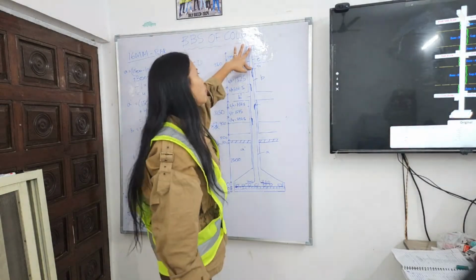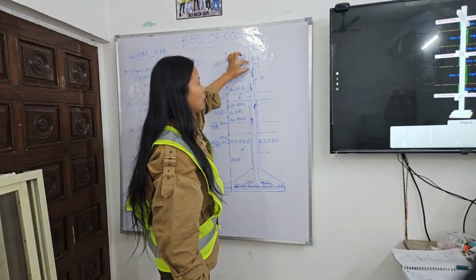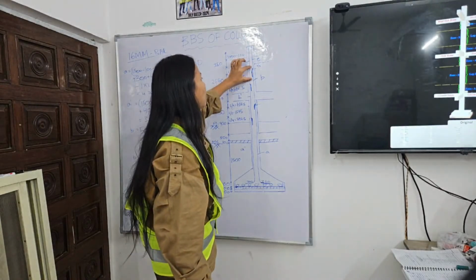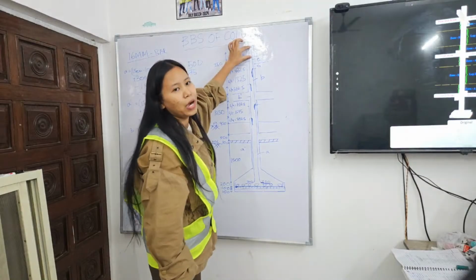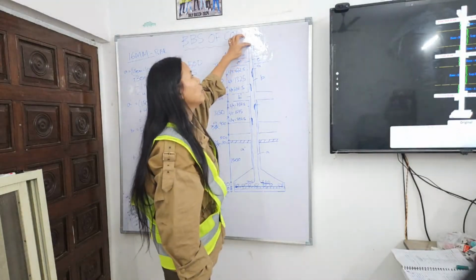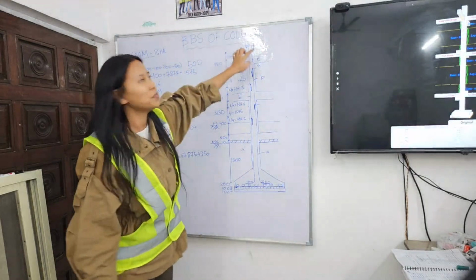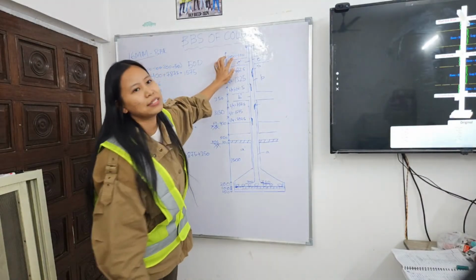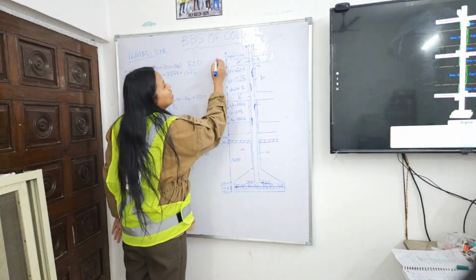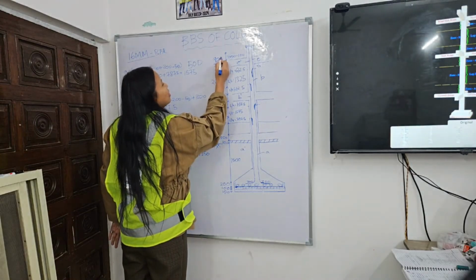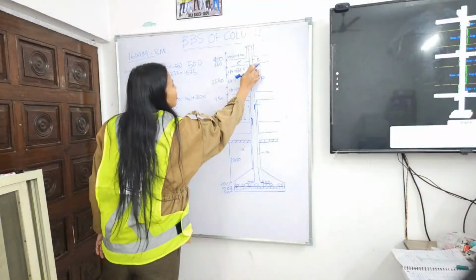Now till the parapet wall, we're going to calculate from here. So for C, we have L by 4 plus the lap length plus L by 4 plus the slab beam, and then comes the parapet wall. When we count the parapet wall, we have 100 mm plaster here. So carefully, 1000 parapet wall, minusing the plaster that is 100 mm, so it will be 900, okay?